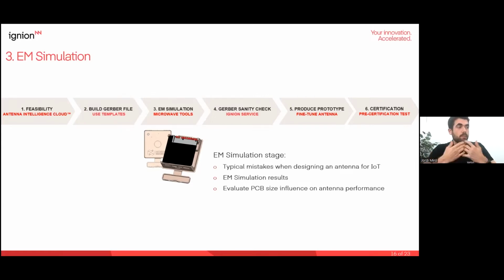So thanks to the tailored capabilities of the built-on antenna, if a change is made in the design, you can follow this with the electromagnetic simulation and then tune the antenna when you are making changes in the design. So design constraints and last-minute design changes can be followed, and you can get back to the desired antenna performance by fine-tuning the matching network.